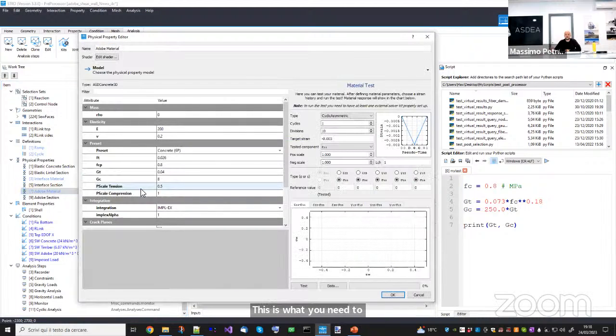When you try to calibrate material parameters for something like masonry or adobe, typically you always have information about elasticity. Something that you have for sure is the FC, and you have FT if you have a shear test, like in that case. The problem is that you don't have any information about the tensile fracture energies and the amount of ductility, because you don't have a cyclic test.